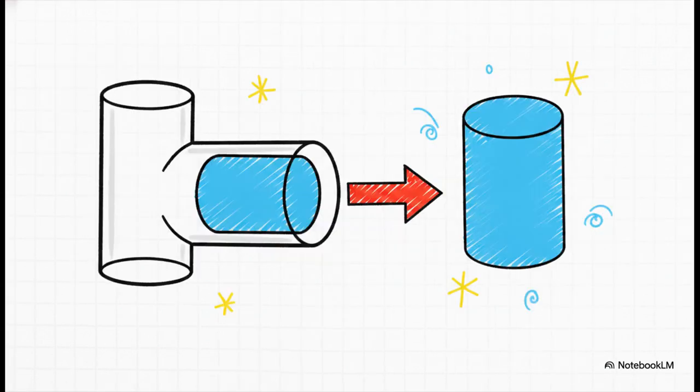Okay, once your solid bodies are squeaky clean, we hit step 2. If you're running a CFD simulation, you need to extract the flow volume. This is literally generating a brand new 3D shape out of thin air, or fluid, that represents the air or liquid around or inside the CAD model.